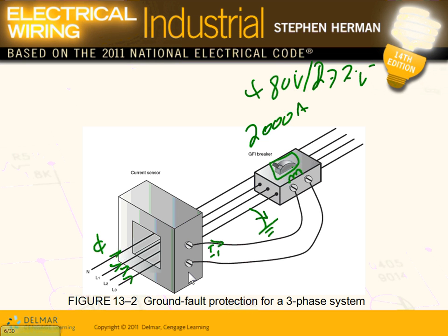It trips fast on a ground fault. It looks for a ground. If you don't put this arrangement in, and you depend on the circuit breaker to see it, it will see it, but not fast enough before the conductors start melting and creating fire.